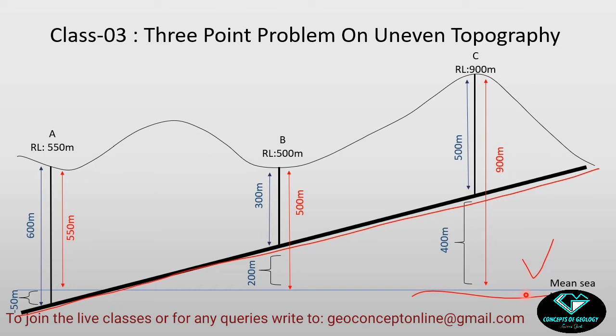So we will convert this depth value, which was measured in terms of this topography, into this elevation value, which is measured with respect to the mean sea level. For doing that, I need this value. If the total is 900 meter and this is 500 meter, then 900 meter subtracted by 500 meter will be 400 meter.